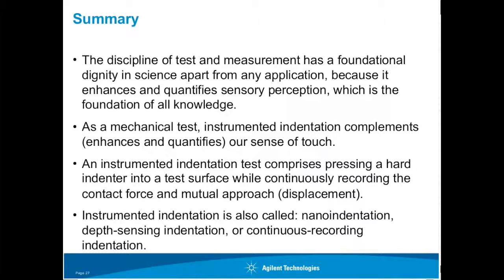An instrumented indentation test comprises pressing a hard indenter into a test surface while continuously recording the contact force and the mutual approach or displacement. Instrumented indentation is also called nanoindentation, depth sensing indentation, or continuous recording indentation, and all those things mean the same thing.